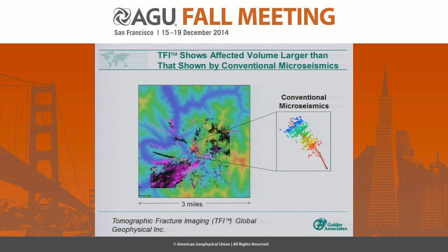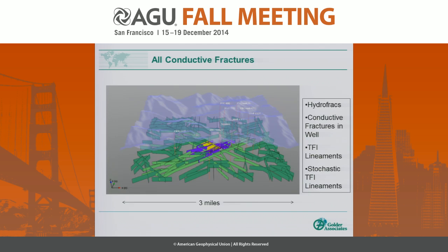And there were tracers put into the gas that were observed in wells up in this area. A farmer who had an illegal, unregistered gas well in this area for his own personal use became very upset when it started to produce nitrogen. So that was down in this area here. So there is some validation that, in fact, the effective stimulation is quite a bit larger than this microseismic footprint.